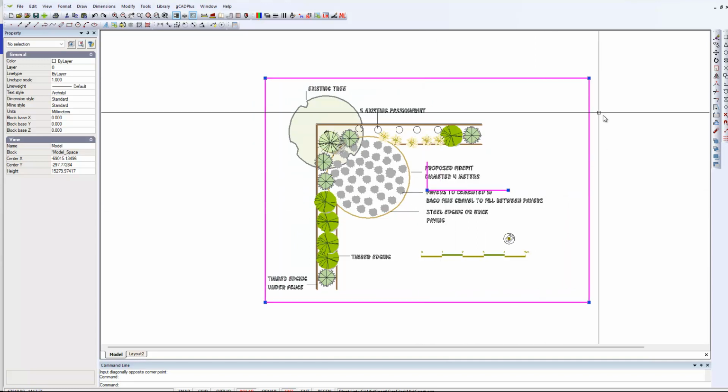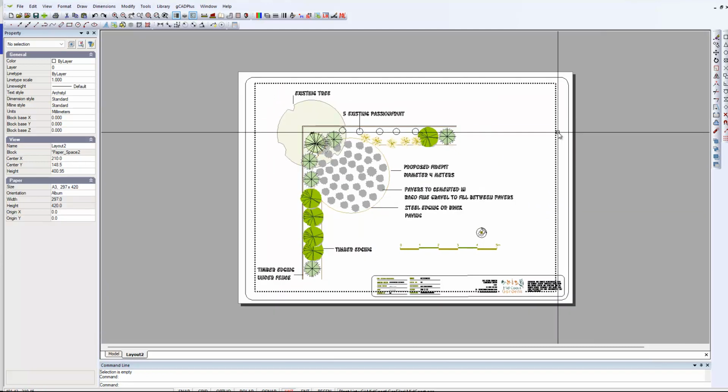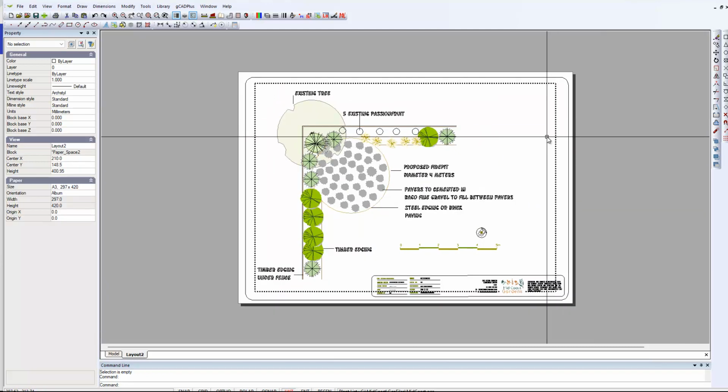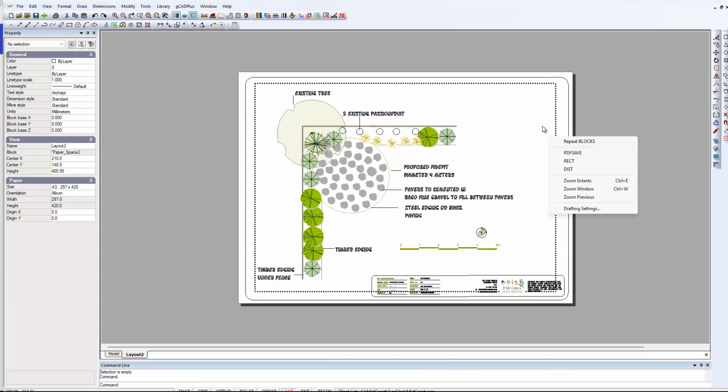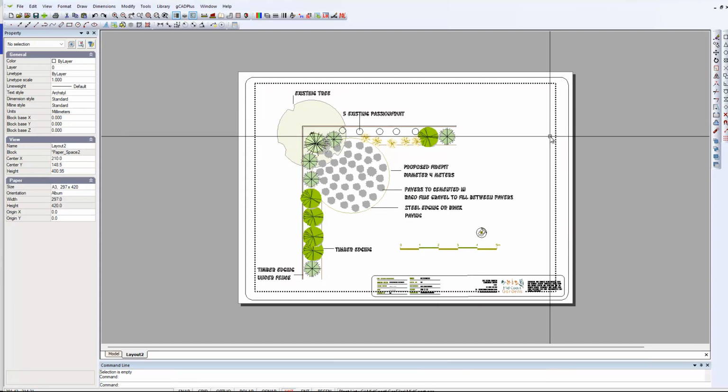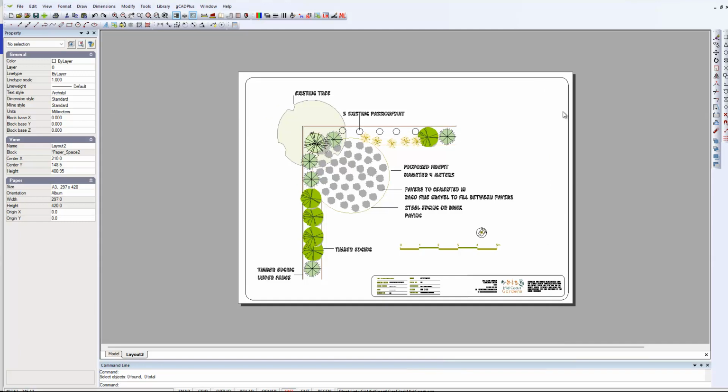I'm just trying to leave some space up here, and now we'll display it on the layout. The best way to remove that dotted line is just to double click inside, and remember that's a floating viewport now with a white background, and we have some space here.